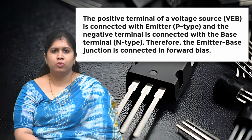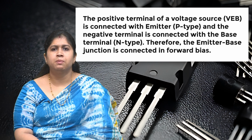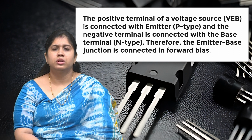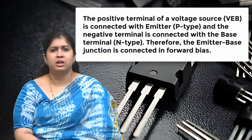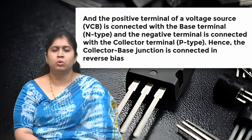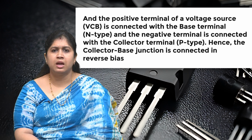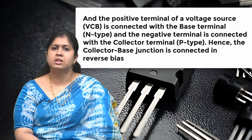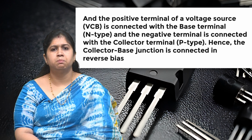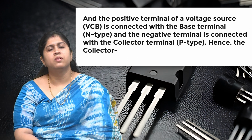The positive terminal of a voltage source VEB is connected with the emitter P type and the negative terminal is connected with the base terminal N type. Therefore, the emitter base junction is connected in forward bias. The positive terminal of voltage source VCB is connected with the base terminal N type and the negative terminal is connected with the collector terminal P type. Hence, the collector base junction is connected in reverse bias.